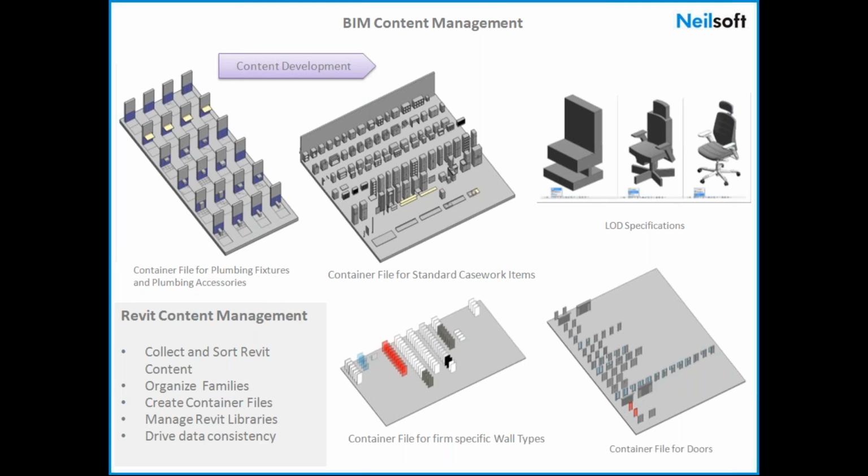That is where developing container files for your families, for walls, doors, or other things, then essentially organizing families, and also developing collaboration tools where the users will be able to get family data from specific locations and not from other locations. This is more to make your BIM model consistent and to make sure that the standards are followed.